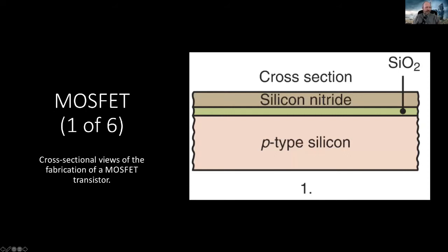Let's just go through the method of making it. So this is how you fabricate it. You start with a crystalline silicon wafer, which we talked about a little bit already, right? It's pure crystalline. It's been doped, making it P-type, okay? And then we put a very thin layer of silicon dioxide on there, and that's done by growing it. You grow the silicon oxide.